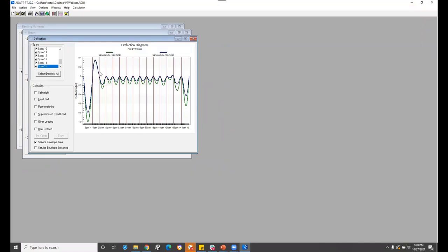And it does look like we have a little bit of an issue here, which doesn't surprise me. This would be an upward deflection, right? And it doesn't surprise me because of this huge span. It's actually causing this to deflect upwards. And I could go back and adjust my tendon control height. If I have some stress wiggle room here, I could do that and try and lower this. For the sake of time, we won't do that.